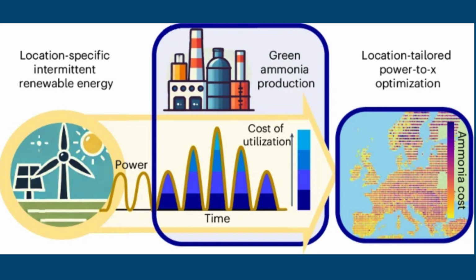The integration of renewable energy with ammonia synthesis also introduces new operational paradigms. Unlike conventional large-scale plants optimized for steady-state operation, future systems must accommodate fluctuating energy inputs. This requirement necessitates catalysts and processes capable of rapid startup, shutdown, and load variation without significant performance degradation. Advances in electrolyzer technology, particularly proton exchange membrane and solid oxide systems, are expected to play a pivotal role in enabling such flexible operation. However, further improvements in efficiency, durability, and cost are required.